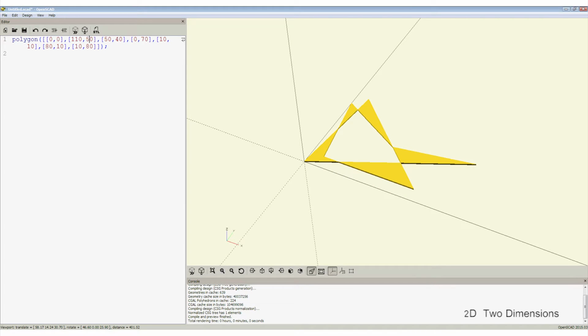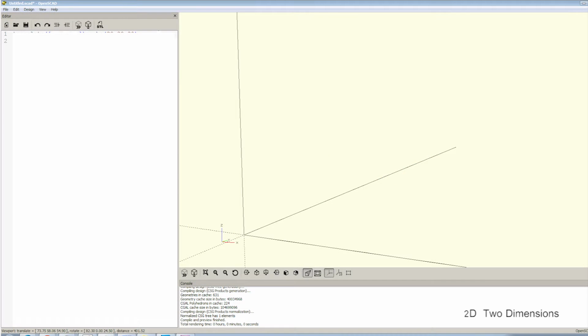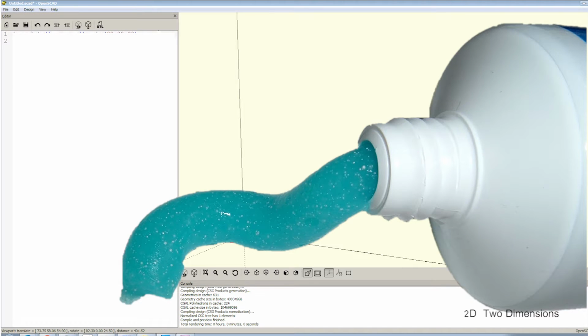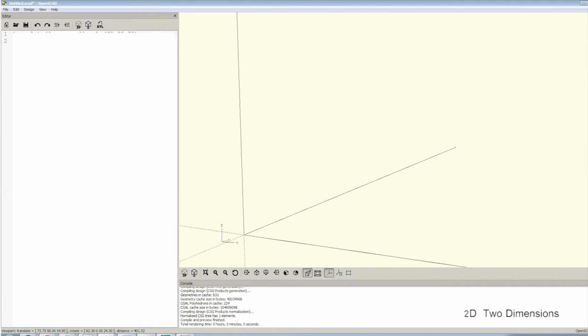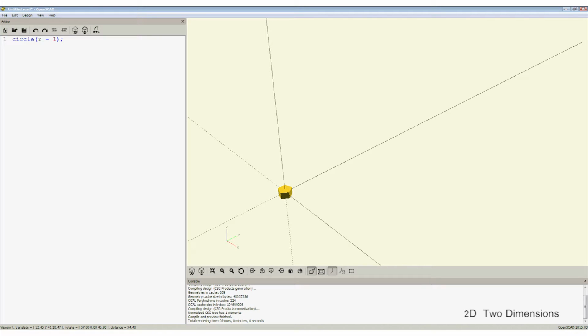There would be little point in using 2 dimensions if it was not for OpenSCAD's ability to extrude. Extrusion forces out the shape into a 3rd dimension, just like toothpaste. We can work through an example given in the documentation to demonstrate what can be done with the extrusion. First, take a plain circle that looks like a hexagon, as this is OpenSCAD's quick and dirty drawing style we demonstrated earlier. Circle r equals 1.